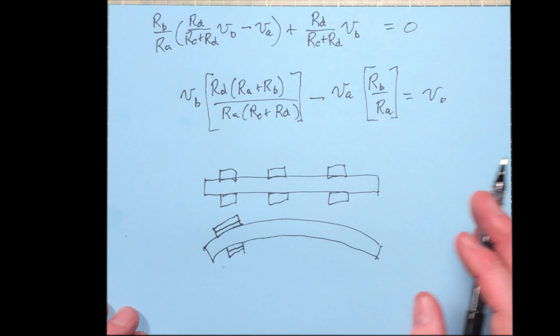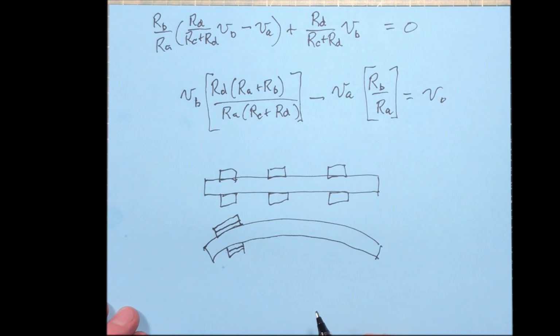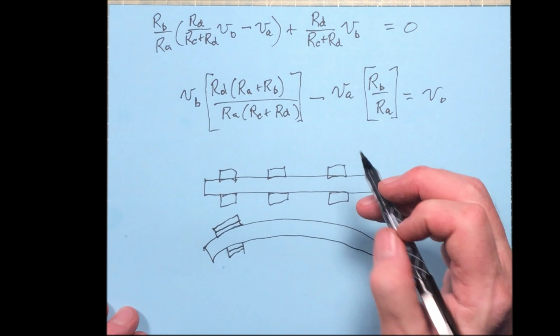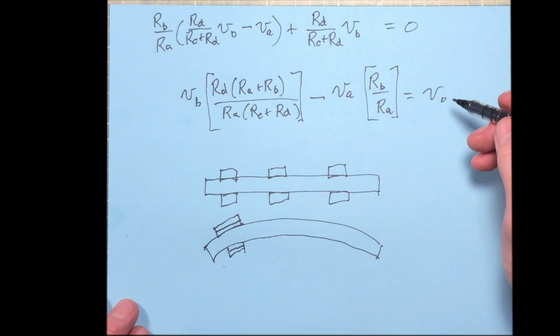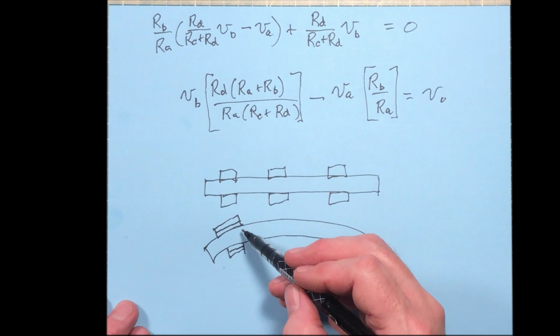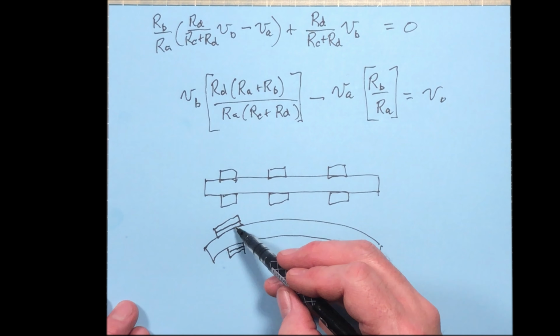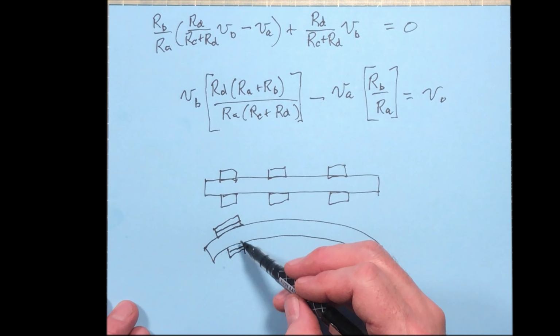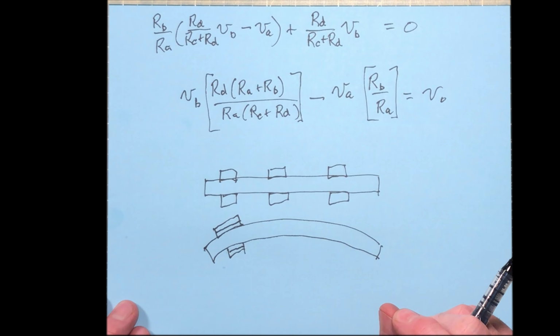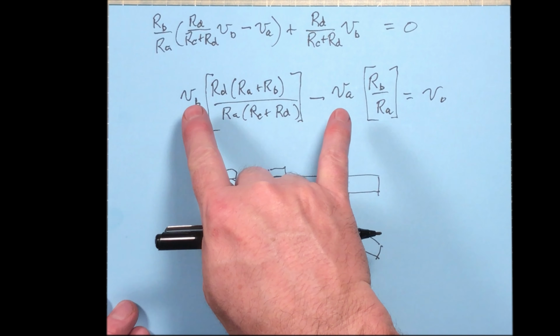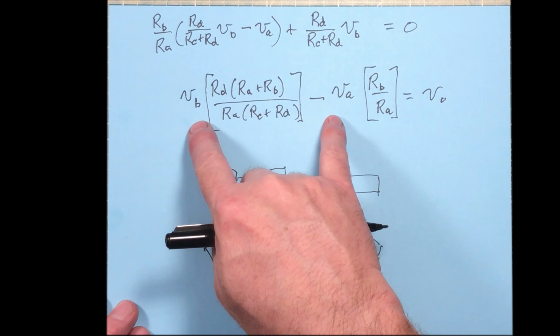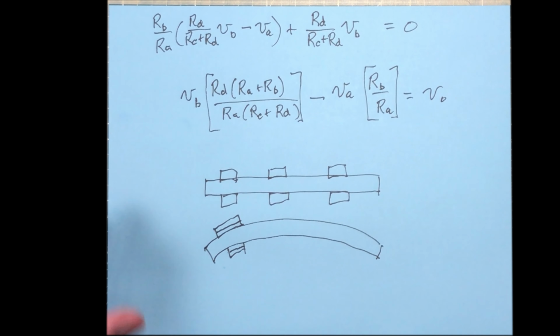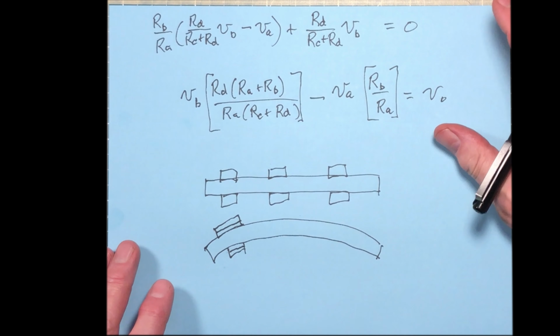It's obviously going to be much more complicated than this simple illustration here, but this is an example of a real life thing that involves an operational amplifier. The difference in resistance between these two, remember I've exaggerated these lengthenings and shortenings tremendously. So the resistance change between these two is going to be tiny. So you need to have some way to amplify that difference in voltage there. An operational amplifier is one way to do that. Okay, at this stage, I think we've finished talking about operational amplifiers in general.